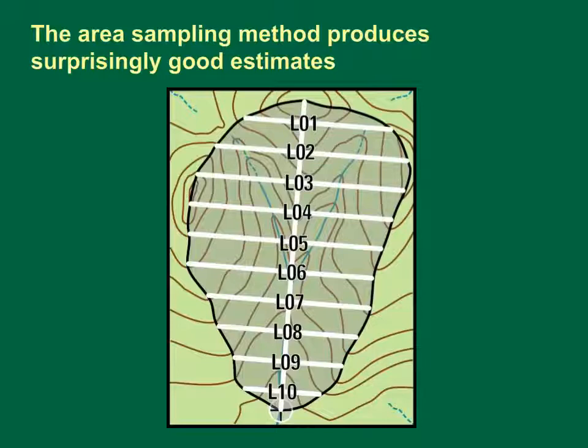To generate an area sampling estimate, draw a line or lines up the center of the watershed. Then draw perpendicular lines at regular intervals. Measure the center line and the perpendicular lines. Multiply the length of each perpendicular line by the distance between the lines and sum the areas. Finally, convert your measurement scale to the scale of the map to get the area. The sampling area for this hypothetical watershed is 15.2 drawing units, and the actual area is 14.6 drawing units. The difference of about 4% is within the national standard of 5% for delineating watershed areas.